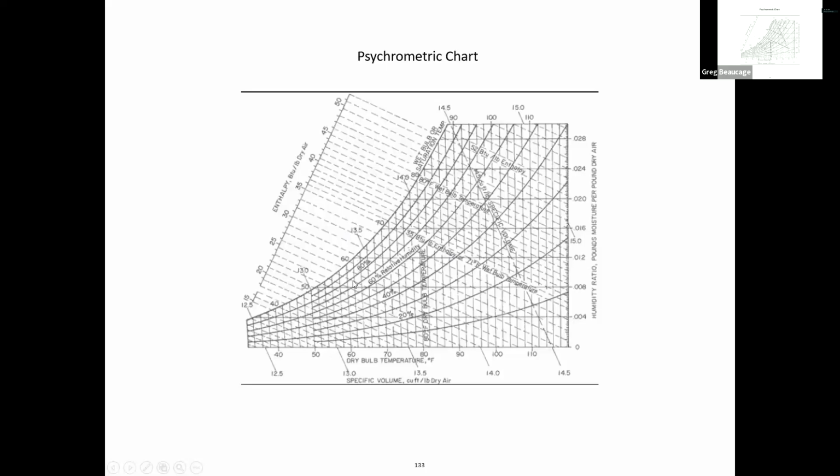If your temperature matches the dew point, then rain forms, right? If you have a certain relative humidity, and you follow the constant isotherm up here, you get the wet bulb temperature. The wet bulb would be following the isoenthalpic adiabatic line, constant enthalpy, up to that point. That would give you the wet bulb temperature.